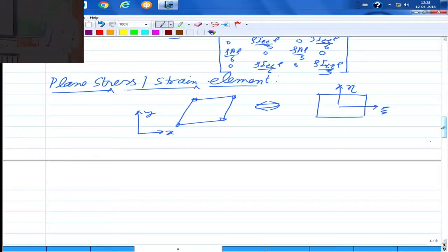In this case, if you look at the velocity and then the kinetic energy, since any point here has a displacement along the x direction as u and the displacement along the y direction as v, you can write kinetic energy as half integration again over volume, and there are only 2 components of displacement, so 2 components of corresponding velocities, u dot square plus v dot square, and then you have rho into dv. So there is no displacement in the z direction.